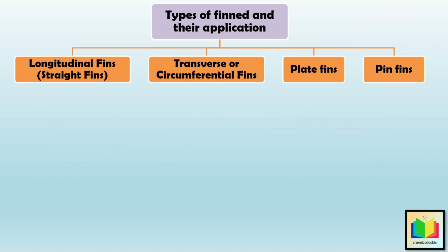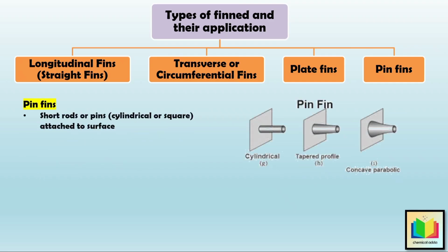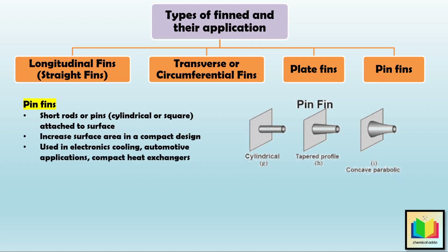Then let's see the last type of fin, which is pin fins. In this type, short rods or pins are attached to a surface, such that they can be cylindrical, square, tapered, or concave in shape. Then the next point about pin fins is, they are very effective for increasing surface area in a compact design. And they are often used in electronics cooling, some automotive applications, and certain compact heat exchangers.